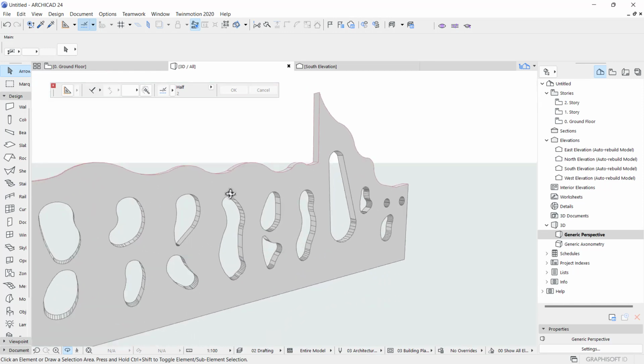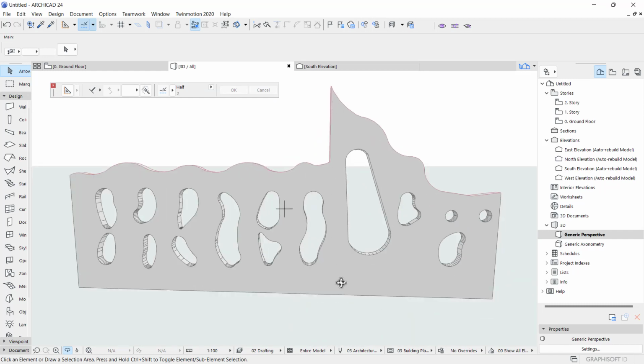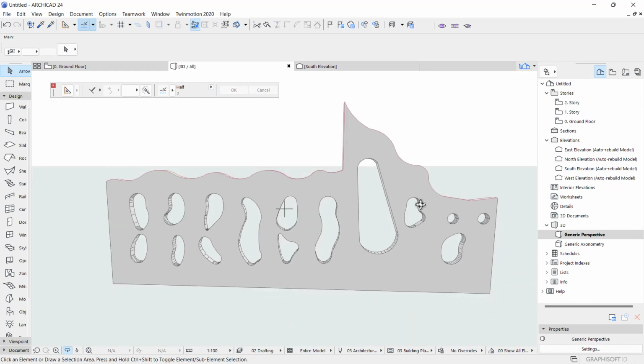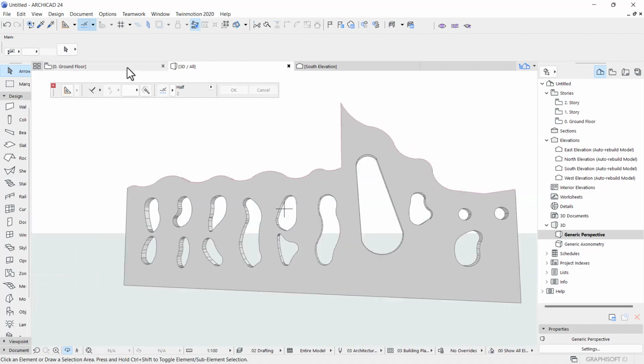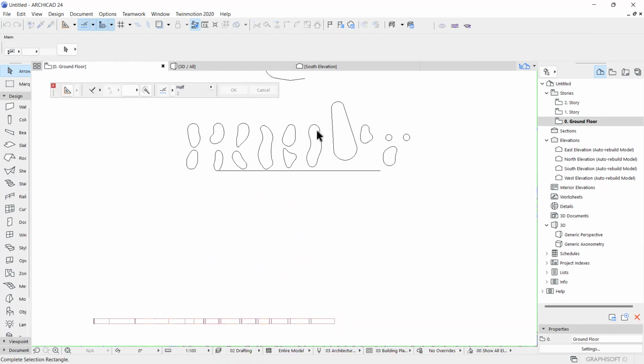This wall is thicker at this point going this way. And like I said, I think I'm able to do it, I'm just tired. But what you can do, if you want that way, is make two windows. One window from here going this way, then another window here going this way. So we draw towards one wall and apply this window here, and the other wall we apply this window here, to make this wall thicker than this, so that we have that difference.